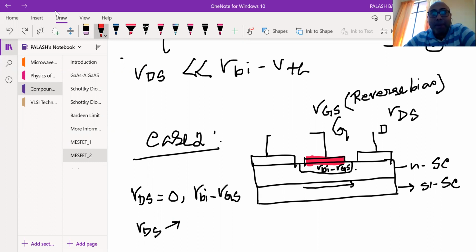One thing you please remember, I have to apply gate voltage in such a way that I can extend my reverse bias condition, so that I can extend my depletion layer. That is fantastic. Plus, on the drain to source side also, you have to apply a voltage. Suppose you are applying a positive voltage, you see this portion, you'll have a reverse bias. So that means the drain side is actually reverse bias, right? So if this is reverse bias, you will understand you have an extension of this part. So please try to check this.